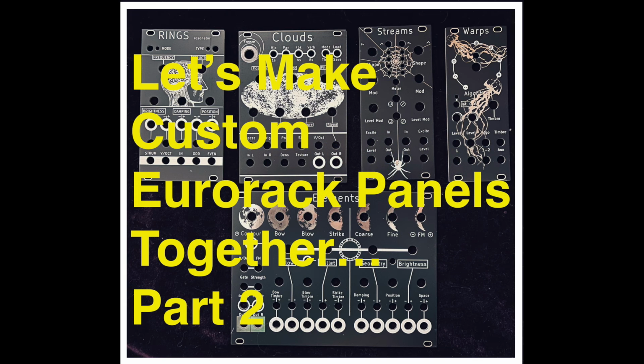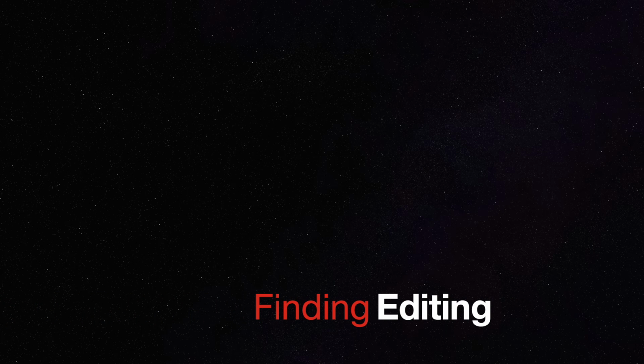So I think 20 minutes is about enough for this video, but I feel like we covered quite a bit in that time frame. We talked about creating footprints in PCBnew, including making your own Eurorack rail mounting holes. We talked about saving footprints. We talked about finding those footprints that you save and editing them.